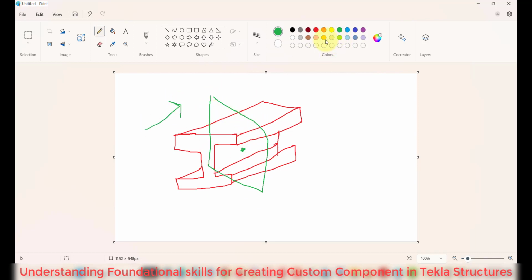Now another center plane can be from the top view. So this is my another center plane. So three center planes will be there. From the top view, the center will be somewhere about here, mid of this height. Then mid of this length will be here, and another one. So top view, front view, and then right view.